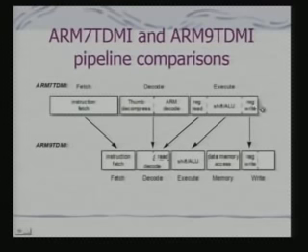And in fact, in the execute stage, I had the register write as well in ARM7. Now that has been split. I have put in an intermediate data memory access or buffering stage and a register write stage, because in many cases I shall be writing the data onto the data memory, which is again distinct from my instruction memory.